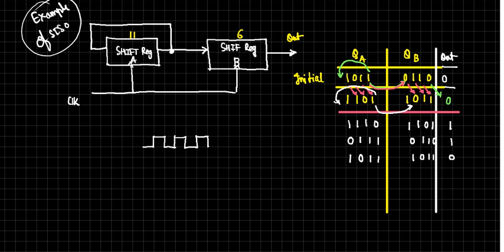It's getting copied after 4 cycles. After that, you should not be doing that. After 4 clock cycles, the data is being copied here. But soon after that, you should not give anything, otherwise that data is gone. To copy 11 to 6, both of them have 4 bits. This was the initial state. It was having 11, it was having 6. As soon as you complete 4 cycles, just because we need 4 bits of information to be shifted or transferred or copied, after 4 cycles you will definitely get the same data.